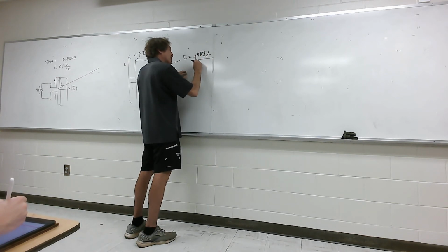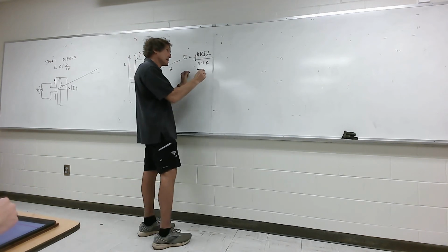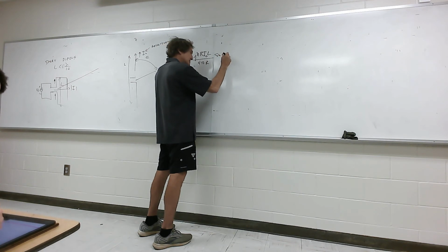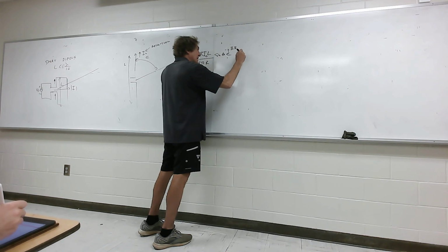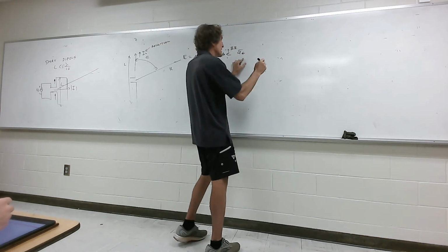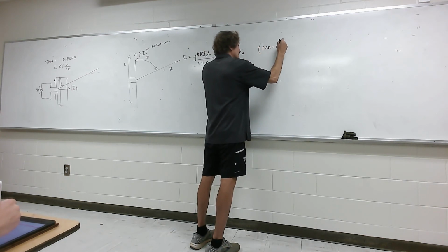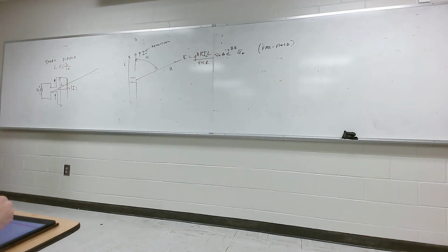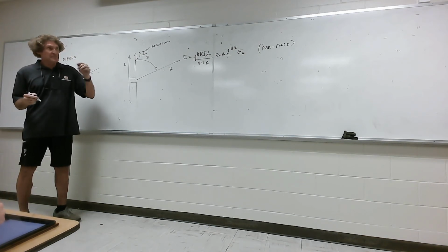Then it's going to be over 4 pi r, so it's inversely proportional to radial distance, times the sine of theta, times e to the minus j beta r, and it would be in the a theta direction. Something I failed to mention, this is called the far field. And I'll explain this now. A lot of this will all come together on Friday, but I just have to get this out there. So this is for a short dipole, that's the field pattern.